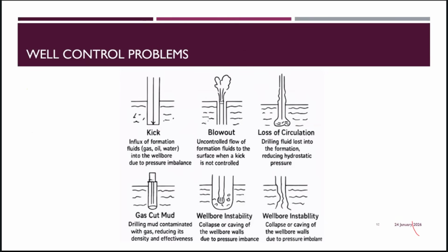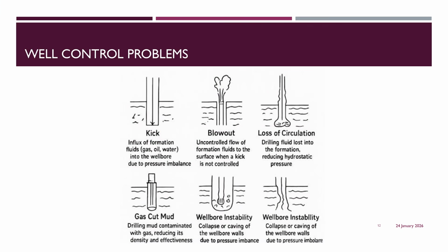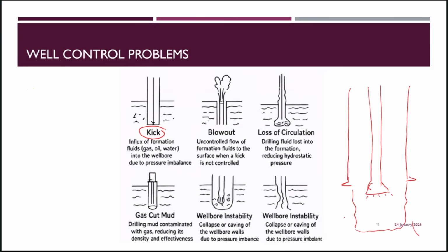One term which you will frequently come across is kick. Now what is a kick? When you are drilling the well, this is your wellbore, this is your drill string, this is the drill bit. Here you have set your casing. This is open hole, and you are drilling. While drilling, sometimes if you go underbalance, fluid from the formation starts coming into the wellbore and accumulates here.